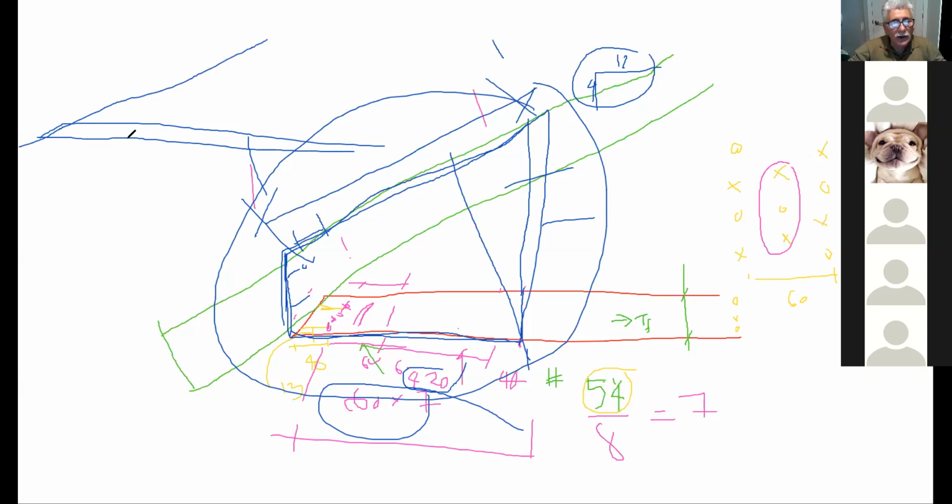And then once you get him this dimension here, what he's going to do is take his piece of plywood, put it in between there, and then take his piece and slap it over there, and he'll be able to draw underneath it and get the exact shape that he needs for his gusset plate. He can even do that.